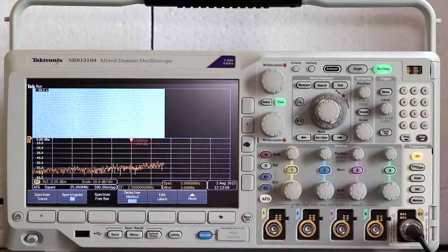If you look closely at the graininess of the spectrogram display, which represents the noise floor, you will see that it is continually scrolling up from the bottom. That is because time is now represented along the y-axis instead of amplitude as in the two previous types of display, time and frequency domains. The x-axis still represents frequency, and we can see the vertical bars in the spectrogram that correspond to the fundamental and harmonics of the depicted square wave.